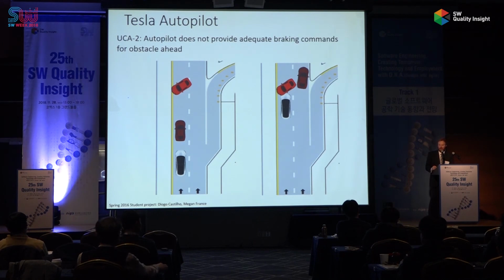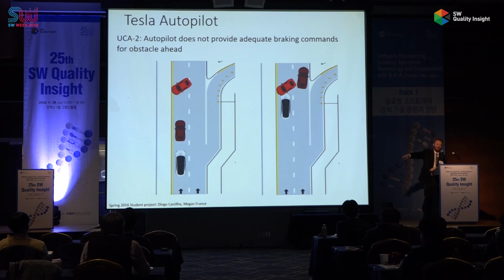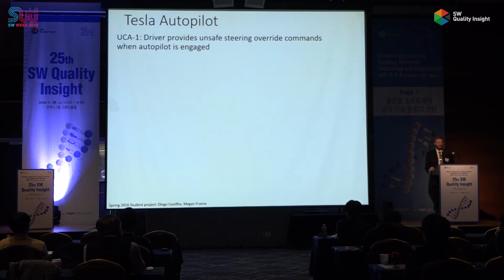Tesla spent a long time trying to fix this in the software. It's very difficult. They found a way to reprogram the firmware for the off-the-shelf radar that they had used to get it to do something it was never designed to do. They got it to steer the radar beam a little bit lower, bounce the beam under the car in front sometimes, and in certain weather conditions, it will bounce back and detect two cars in front, but not always. Not a very good solution. If we had identified this earlier, we could have done something much, much better, and it would have cost a lot less. Here's another scenario that they found.